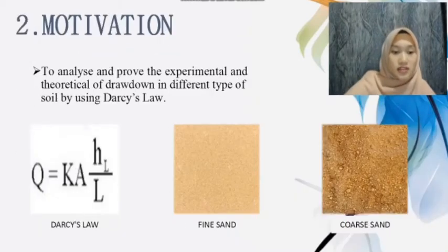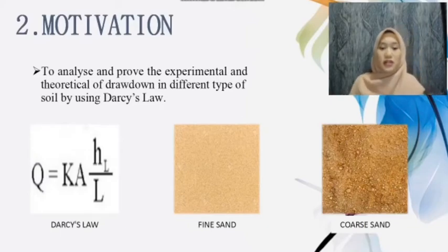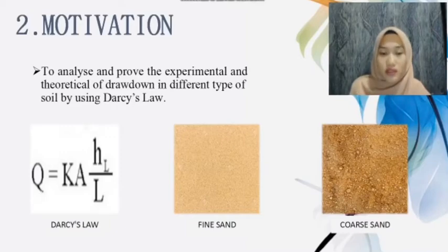Next is motivation. The motivation of this study is to analyze and prove the experimental and theoretical drawdown in different types of soil by using Darcy's law. Typically, monitoring of groundwater level due to water extraction or pumping in an aquifer is important as a fundamental for groundwater resources management. In order to study this effect in a groundwater aquifer, the hydrology apparatus was used to analyze the drawdown of groundwater pumping with different sizes of sand, which is fine sand and coarse sand.